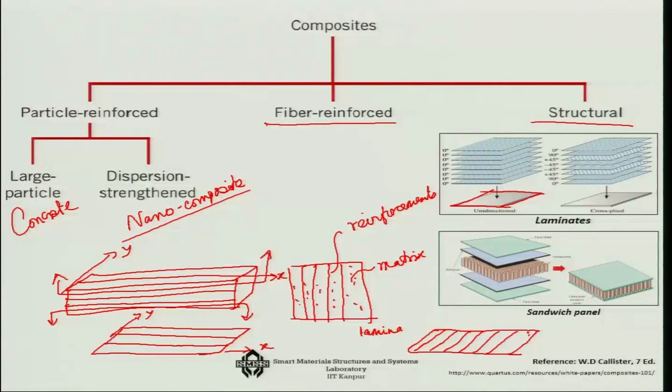So, here the angle of the ply, the angle theta, equals 0 degree, because with respect to the x axis or the longitudinal axis, the angle of the reinforcement orientation is 0 degree, whereas here with respect to the x axis this is 90 degree, and hence this is a 90 degree ply.